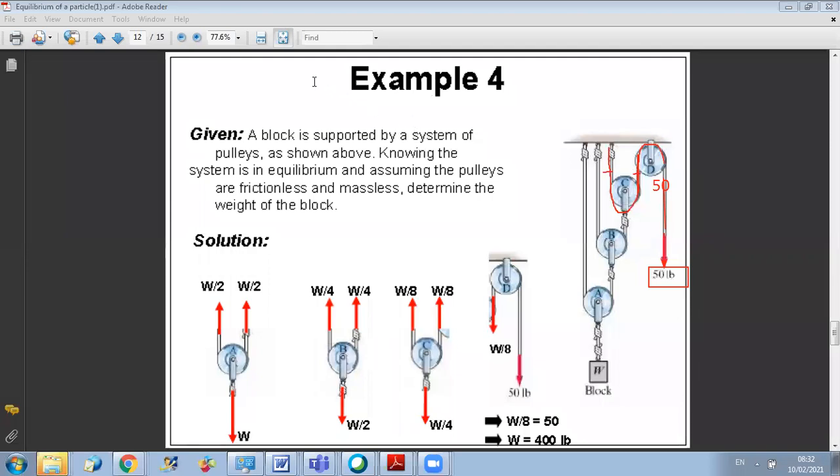Okay. Now, once I did this, I can consider the free body diagram of pulley C. If I want to isolate C, I should cut like this. So I am cutting at 3 places. Here, I am cutting the first cable at 2 points, the first time here, the second time here.